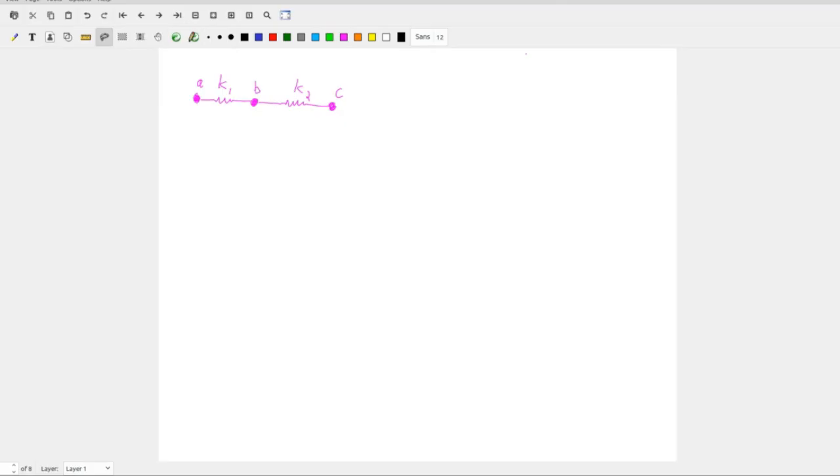How about that one? You want to do the springs in series? Okay. So, Nick, if I pull on C, is my deflection in K1 and K2 going to be the same? I believe so. All right. So what happens if K1 is stiffer than K2? The more deflection is going to occur in K2. Yeah. Right. So they're not always going to be the same. They're only the same if the stiffness is equal.